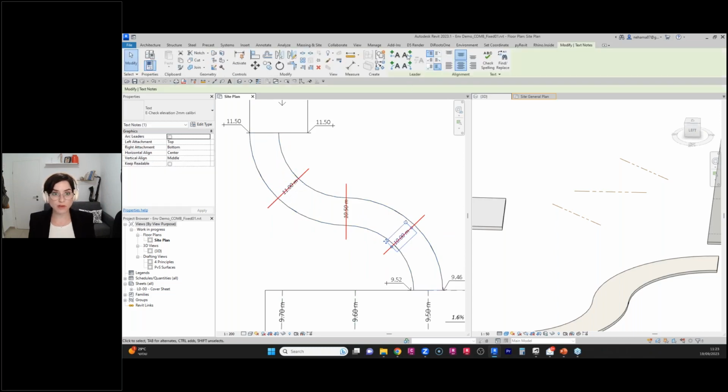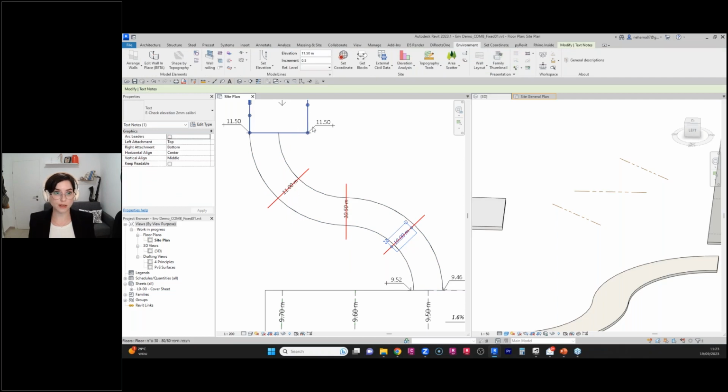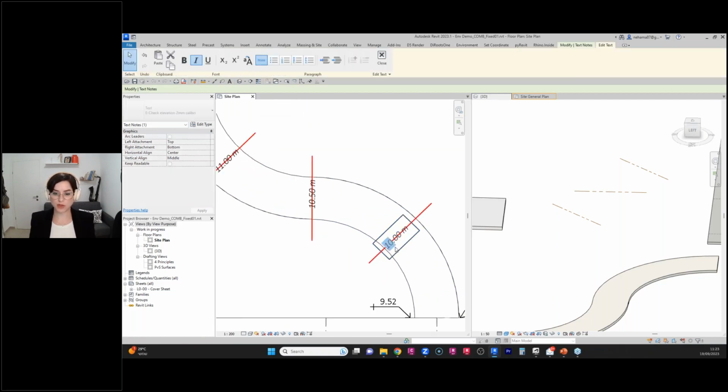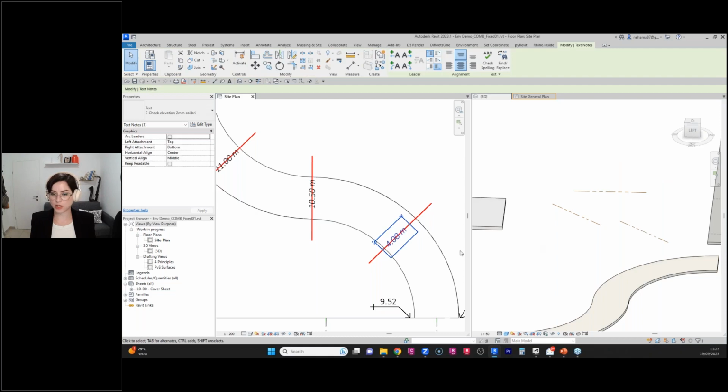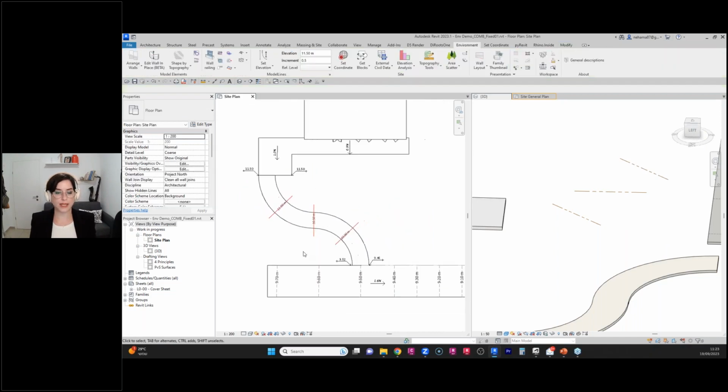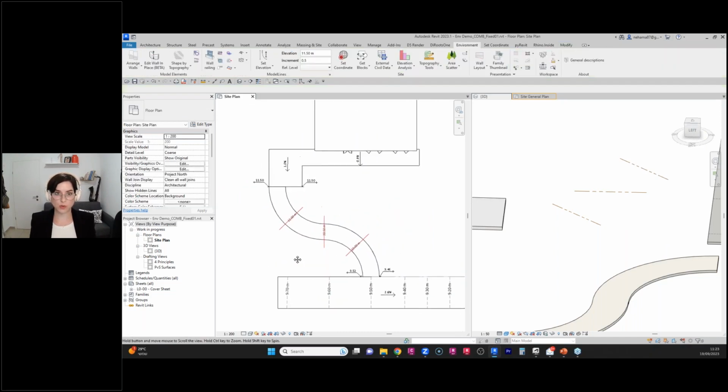If I want to change my elevation, I don't have to go to the set elevation tool again like before. I could just type the elevation that I want to change. So let's type 4 and take a look at my 3D view again. It's going to change. And then I can bring it back. So again, it's very simple, very intuitive. Just place a line and decide what is the elevation that you want to give it.